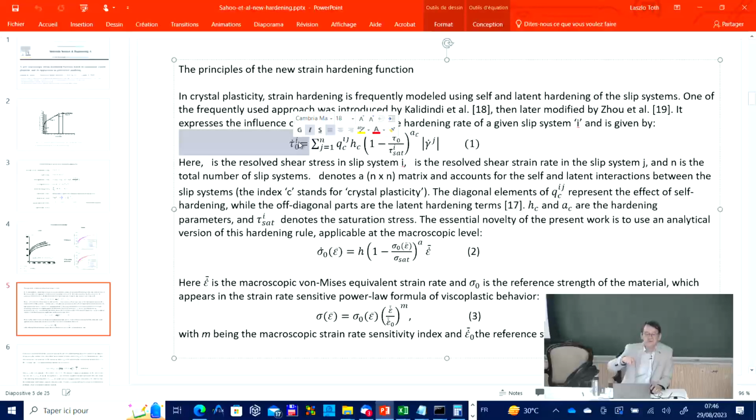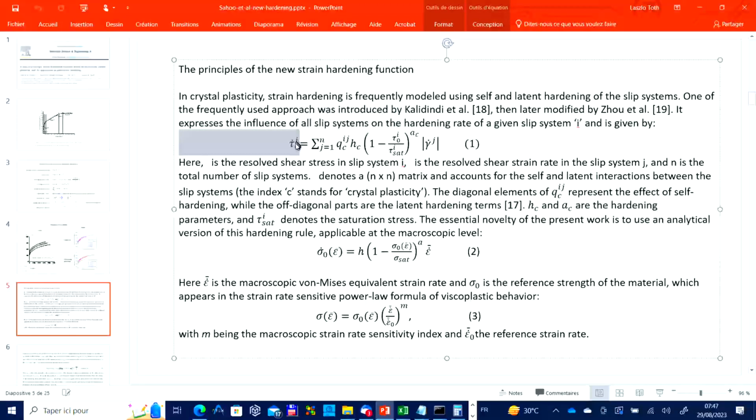But this is a value at slip level and in many grains, you know. And the macroscopic value we get actually by doing a simulation, just one step. And we also get the Taylor factor this way. So this is actually the point of the whole business that we have been doing since already now, second day, to fully control the strain hardening. But this is a very general approach that I repeat, you can use afterwards in any kind of strain mode.